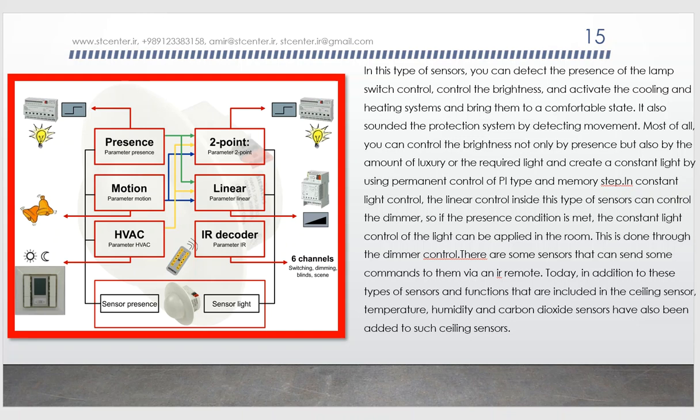Okay, we can make the building much greener on the energy side. So it is better to use the light controller with presence detection, because if persons are present in the room, then the sensor tries to reach the desired set point we set for it. But if there is no person, why should we try to reach the set point in light?